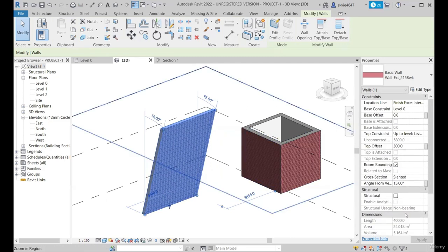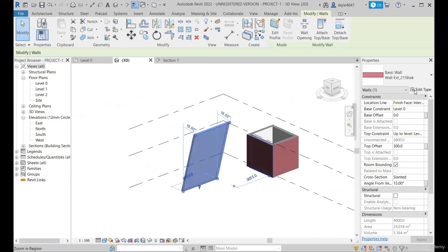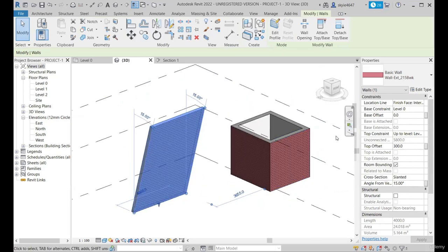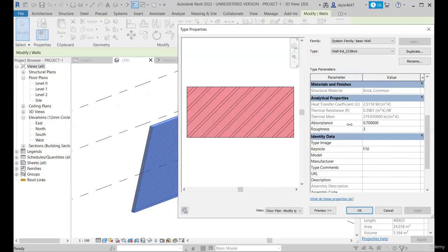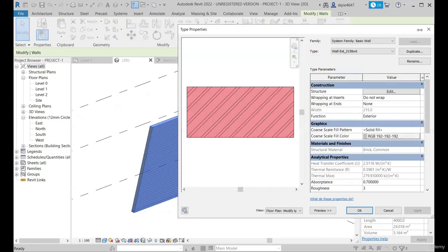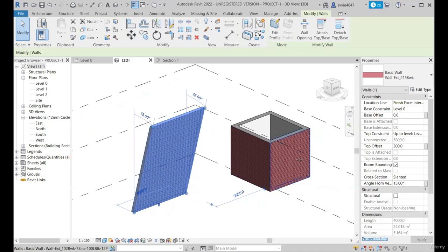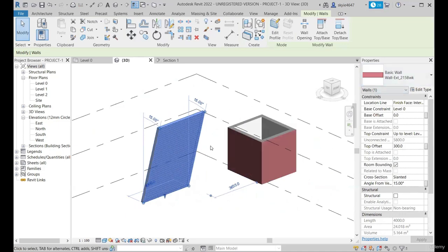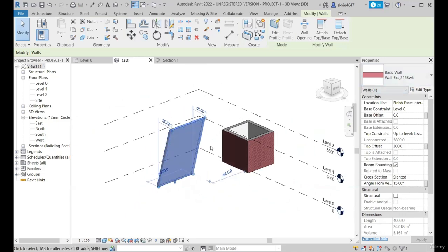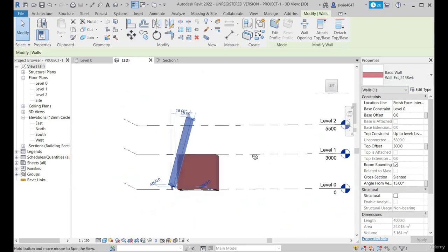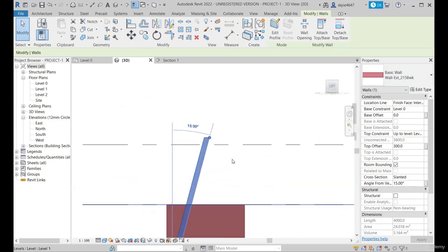These are instance parameters and depend on a single entity, not all of them together. If you want a single change to be reflected everywhere in all walls of that type, then you need to go to edit type. Any changes there will be reflected to all the elements of that particular wall type. Okay. Let's not worry about it; we will brief it as we progress through the course series.